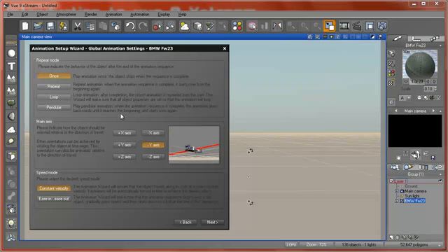Okay, so now it asks me about the repeat mode. If I want to play an animation once or repeat it, loop it, or pendular, so it plays the whole animation, then it plays it backward. Okay, now I'm gonna choose repeat maybe. In this category, it asks me about the main axis, which is how the object should be oriented relative to the direction of travel. So here it's on minus y, but I want it to go on the minus x-axis, so here it is.